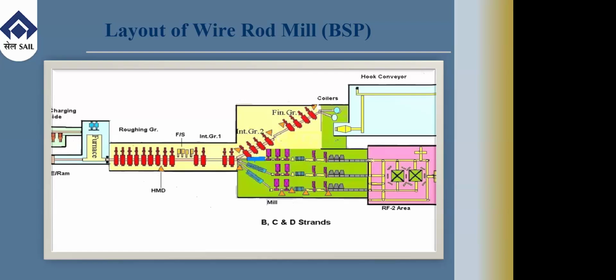This multiple cuts issue, yes, we accept that in certain cases it is there. As Madam already told in the presentation, it is a chain conveyor where these coils are carried after the laying head. So sometimes a coil gets entangled in the chain and it has to be cut. We try to segregate such coils from the prime material, but it is not possible in 100% of cases, because sometimes these cuts are hidden inside the coil and are not visible during inspection from the outside. So yes, we accept that in a few cases it may be there.